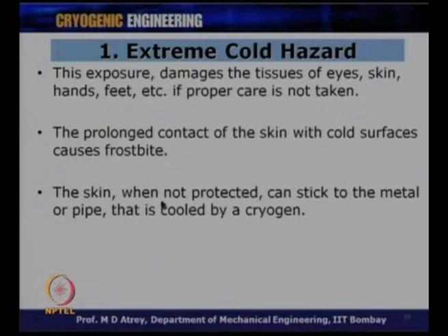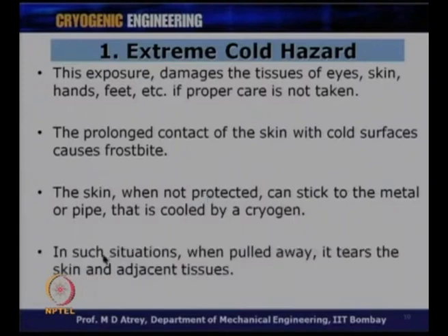So, it can be really, really fatal, and you must see to it that your skin is not touching those pipes or surfaces which have cryogen underneath. It is a very important aspect. In such a situation, when pulled away, it tears the skin off and the adjacent tissues, which is going to be very, very fatal in many cases.